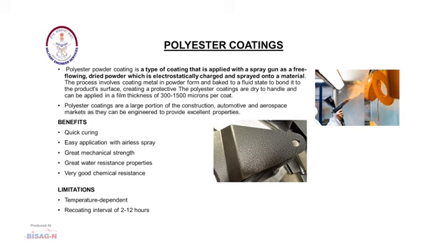Benefits: quick curing, easy application with airless spray, great mechanical strength, great water resistance property, very good chemical resistance. Limitation: they are temperature dependent and recoating can be done after an interval of 2 to 12 hours.